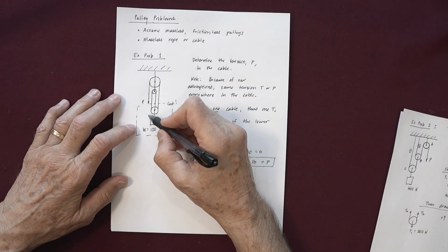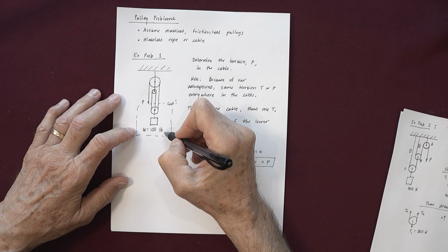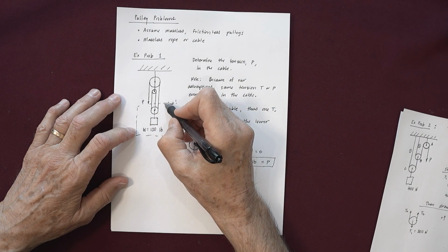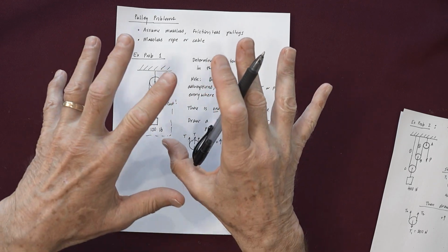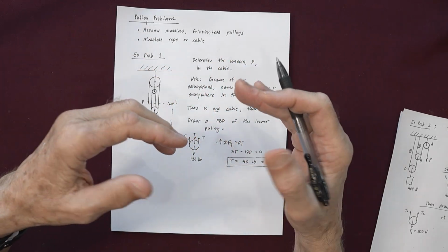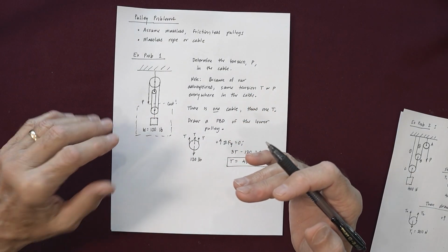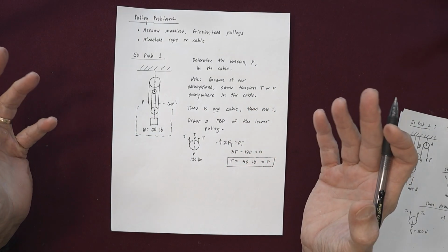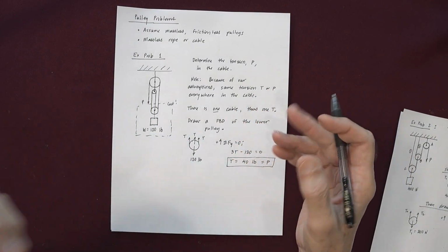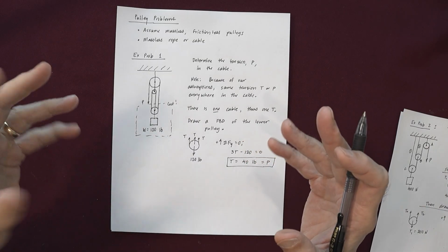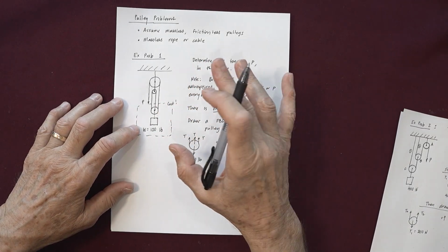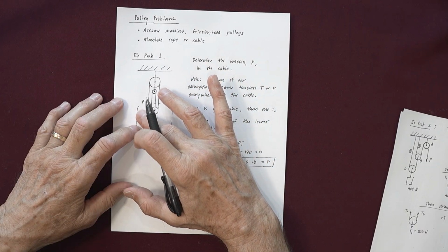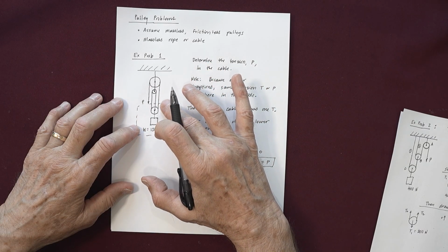So what you do, start at the end where you're given a weight or something, cut these cables, and find these internal forces. Remember, cutting something or sectioning something exposes forces. The method of sections, or cutting something to see internal forces, is a critical step. Ultimately, you can argue that this problem as drawn is not solvable.